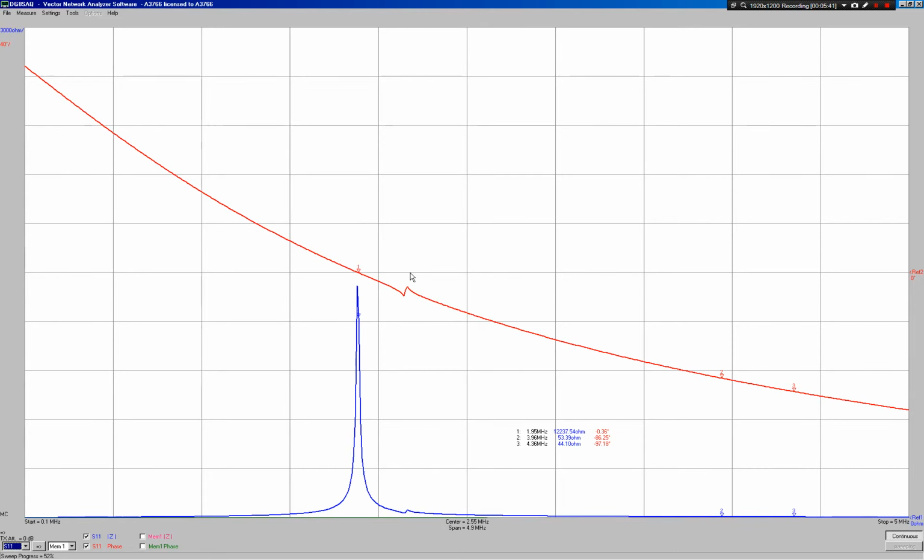Bringing it closer, that phase change is starting to grow now, and we also start to see the impedance starting to change down here. That phase change is most likely attributable to the wire length. That's the fundamental resonant frequency of the secondary, at the phase change at which that occurs. Let's just put that in there, 2.21 megahertz. That is what we would expect. And they're now at a distance of just over 30 centimeters. Bringing them closer.